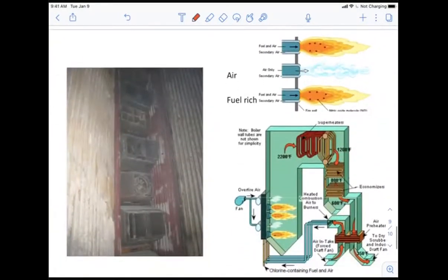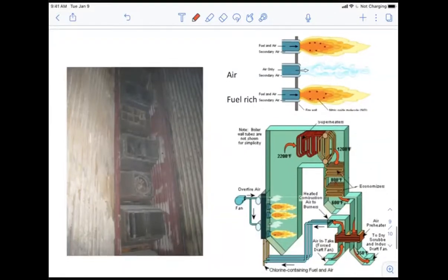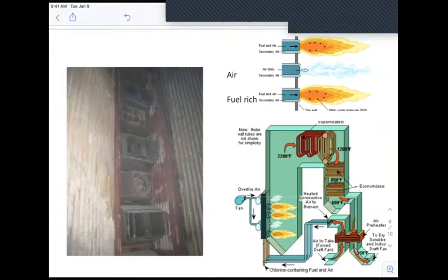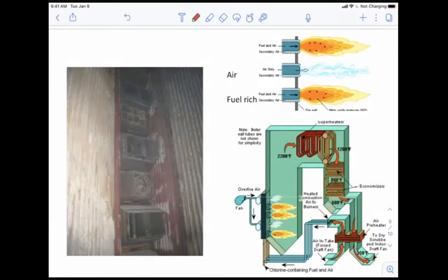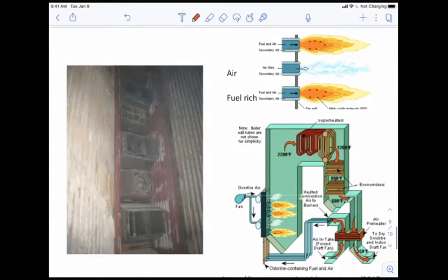So as I said, there could be many ways to control the NOx formation, right? And one of the most important control methods is actually the overfire air. So I just drew a very simple schematic diagram earlier, but what it really looks like is that we're just introducing more air into the combustor. Okay, so this is overfire air, and it's being introduced from, let's say, these nozzles here. Okay, and below this air are going to be the co-combustion nozzles, right?